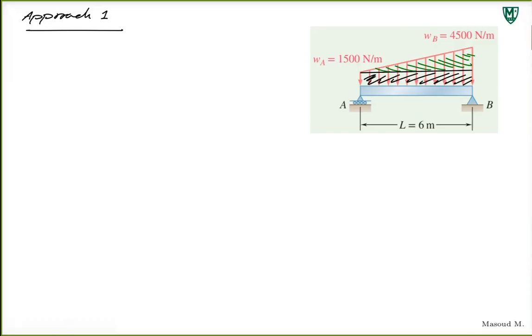Let's form that table. Remember, in this case, I'm only trying to find where this load should be located along this one direction. So I don't care about y. Load is a sliding vector, it can be anywhere in this direction. So all I'm trying to do is find this, let's call this x. I want to know how much this concentrated load should be, its magnitude, and where it should be located.